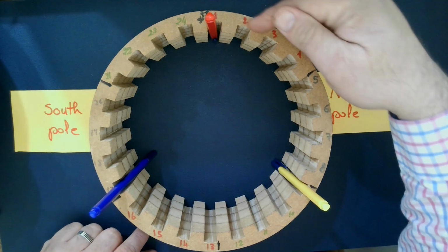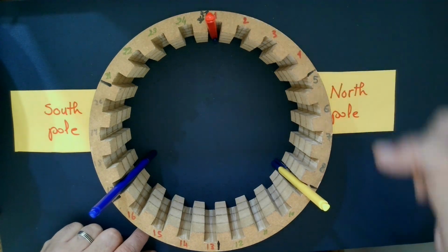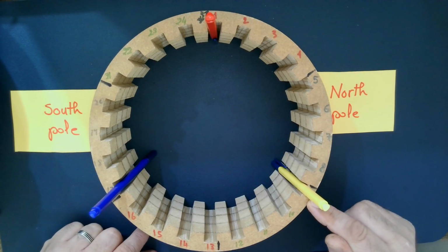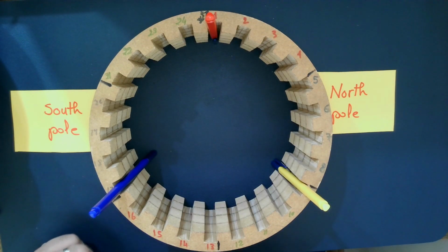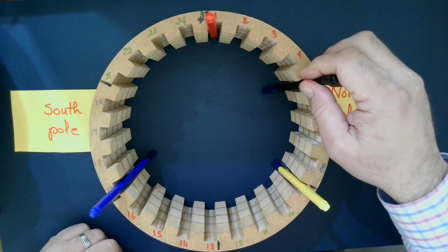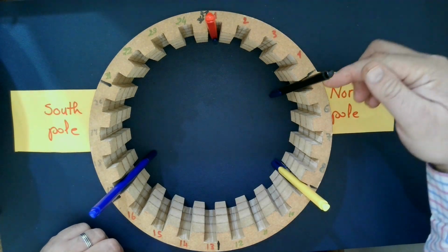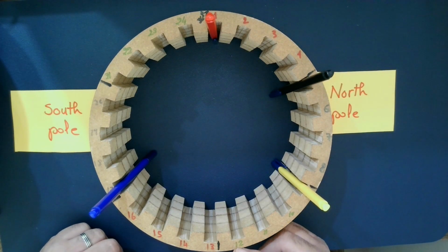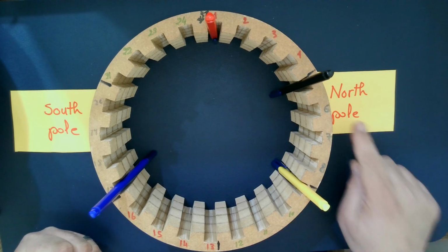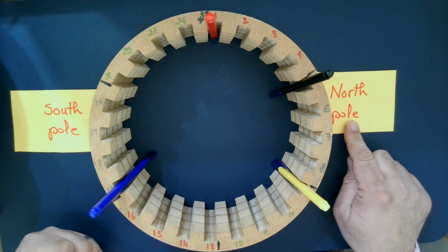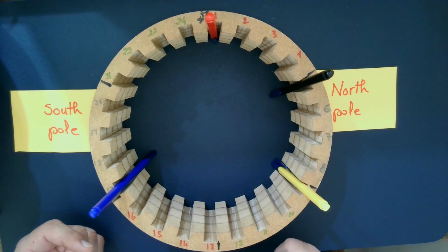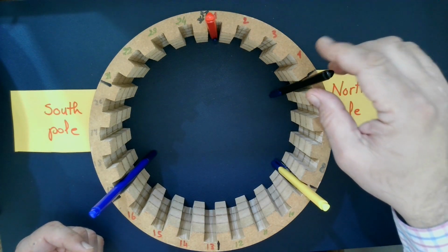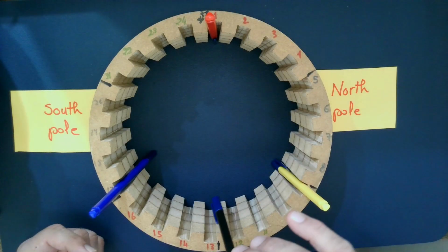So under North Pole now we have A and B. But the condition said that under each pole we should see all phases. The return of phase C will be 180 degrees from that one. So this one will be C dash. So we have A, C dash, B. So now we satisfied the first condition: each pole should accommodate all phases. And the second one, the start between adjacent phases is 120 degrees. And the start and finish of each phase will be 180 degrees.